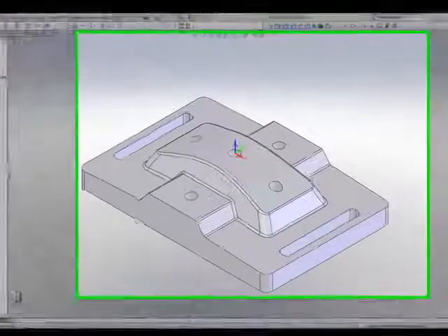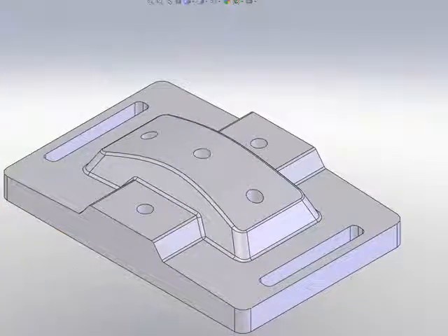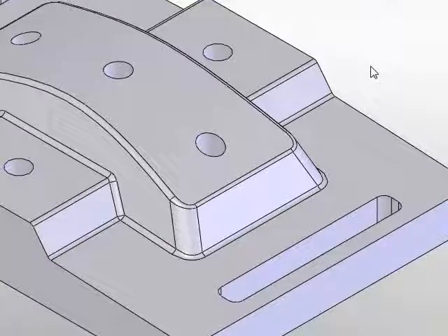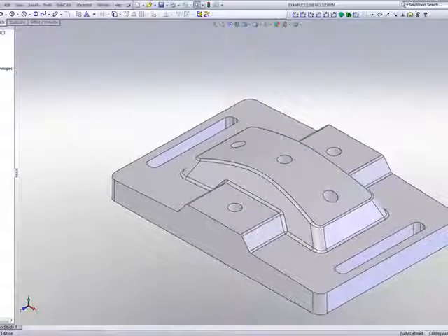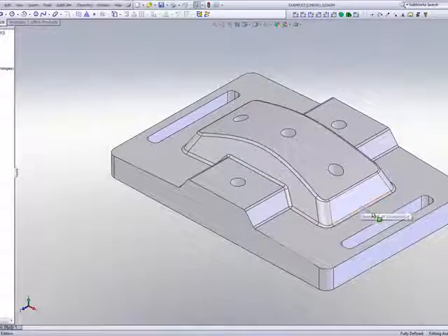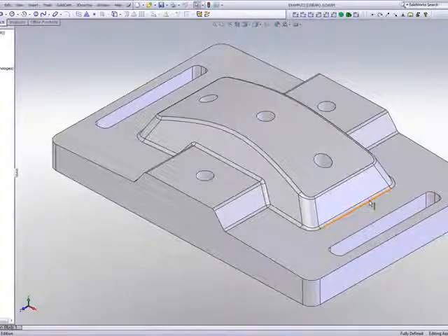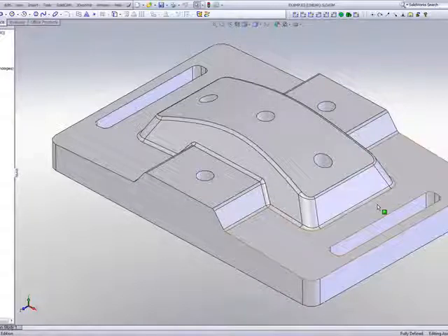In this next part, I'd like to demonstrate some of our finishing options that we have in HSM. Now, what's special about this part is the fact that I'll be using in the beginning a large ball end mill, an 8 millimeter ball end mill, whereas these radiuses over here are only 3 millimeter radiuses. In other words, the actual radius of the tool is bigger than the radius over here, and we would like to go in a smooth cut up these walls as shown over here.